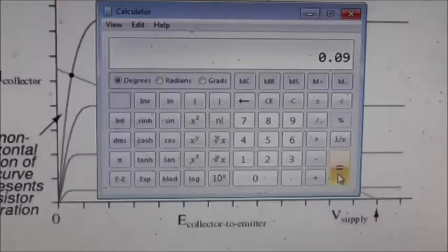Now, the buzzer wants 0.03 amps to operate efficiently and properly. So we're giving it 3 times more current than it actually needs. It'll only take as much current as it actually needs, and so the other 2/3 of current there are redundant safeguards, which means that the buzzer will work efficiently and properly regardless of what the voltage, and therefore the current, actually does. So we're keeping the transistor conservative, we're keeping the switch conservative, and in that way we should get no dropouts.